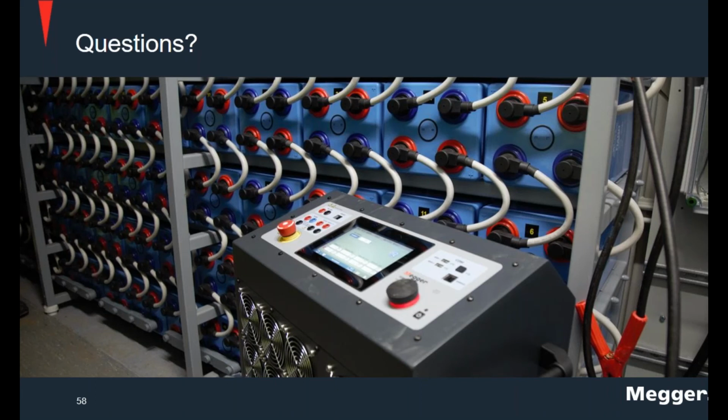Once we reach 100% charge on the battery, we should start counting 72 hours for the battery to be ready to run not only discharge or load testing, but other measurements like impedance. And this is to allow the battery to stabilize after the charging process. So again, after you reach 100% charge, that's when you start counting the 72-hour period for the battery to be ready for testing.